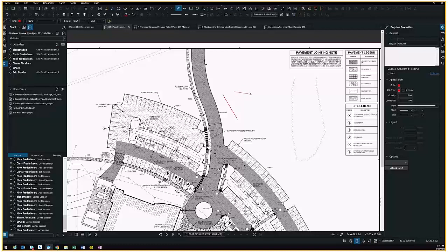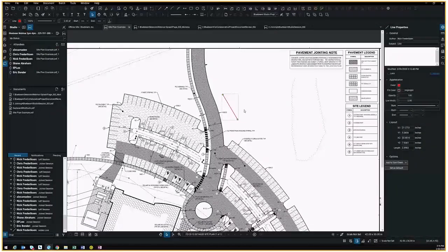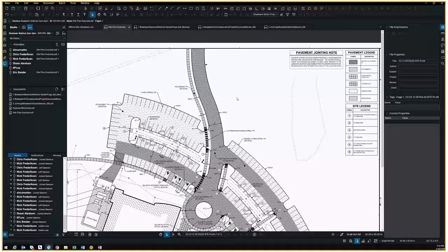If you need to draw on a polar aspect, if you hold in shift, it will quadrant and quarter quadrant out for 45 degrees for you, just to clean up your markups a little bit. Like I said, the markups can be very in-depth and they can be very rudimentary, just depending on your level of use within Bluebeam.